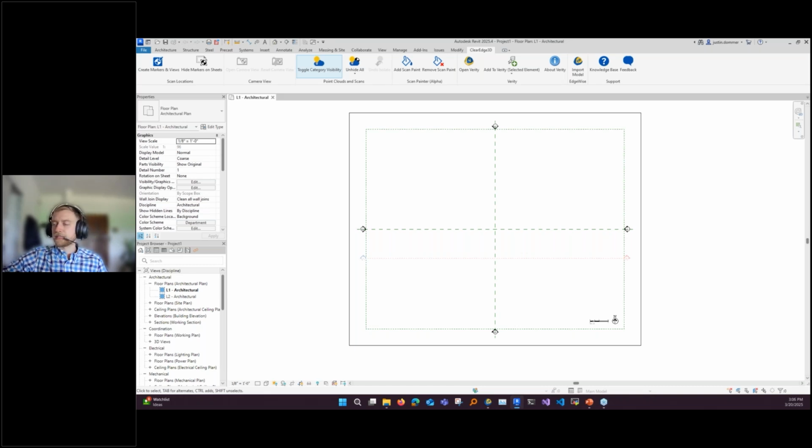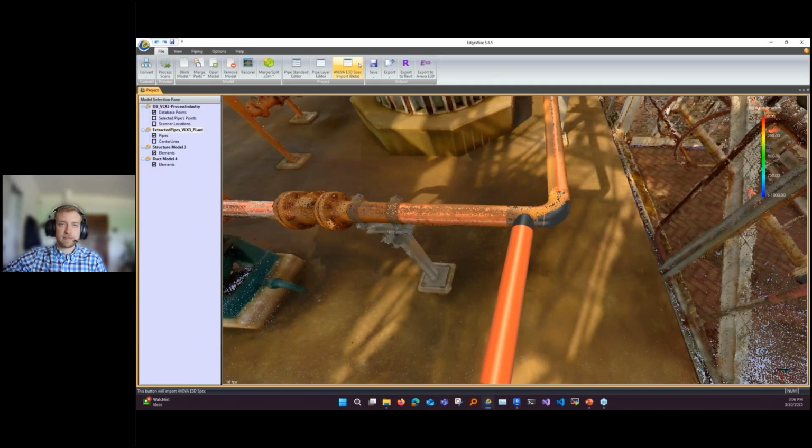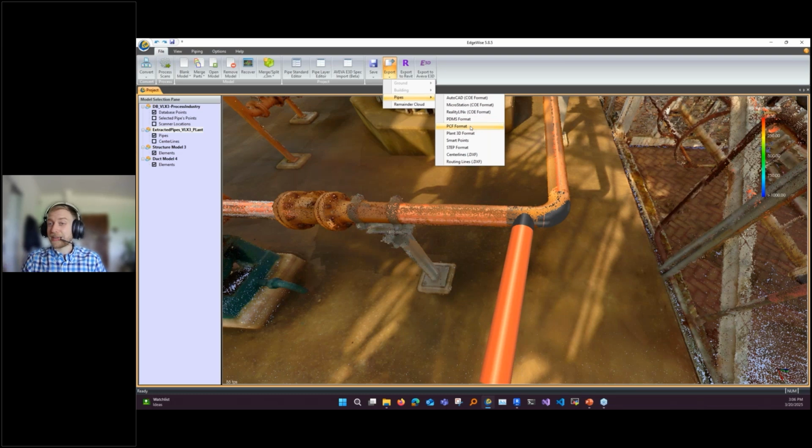Okay, so let's see. CADWorks. Yes, we do work with CADWorks with the PCF export. It's been around a long time, but we do have PCF. It was made for CADWorks. And I believe there's a function you can import it in, and then there's a command to basically convert to native geometry. I don't remember what the command is off the top of my head, but we can help on the support side for giving more explicit instructions, but it's basically PCF out.